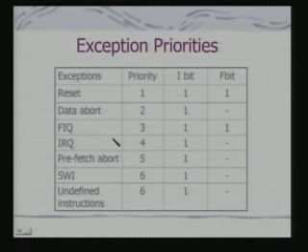When FIQ occurs, you will find that both the I and F bits are disabled. That means, if I am servicing FIQ and I do not explicitly enable the F bit or the I bit, another FIQ cannot be serviced.